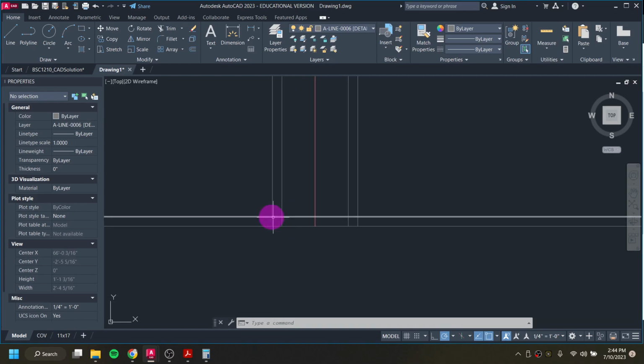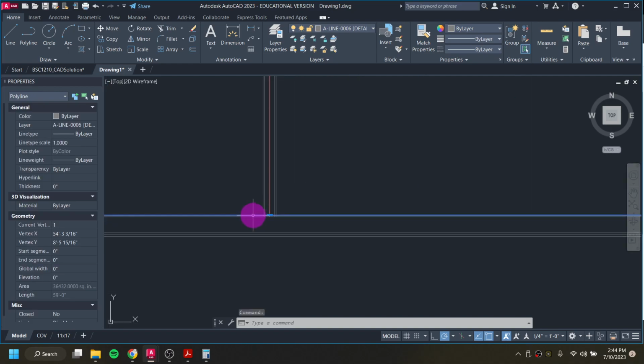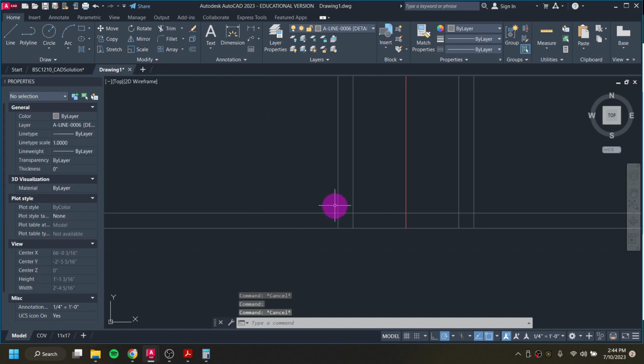Now we're going to clean up these corners with our trim tool. Also, in the case of this corner here, we could use fillet. I wouldn't do it in this scenario. I'll show you in some other cases where it would be more beneficial. But since this line goes all the way across and is this big polyline, I don't think it would really be that great here.